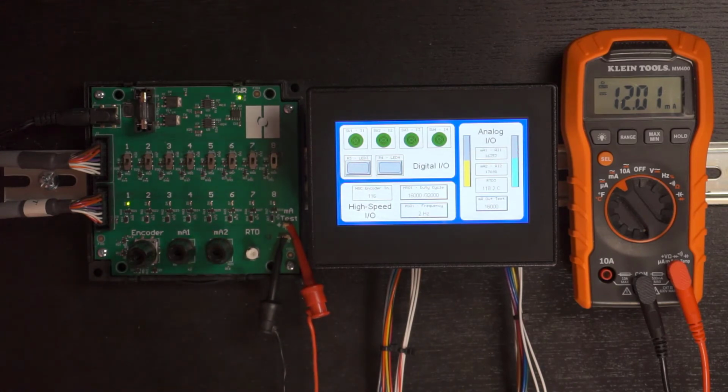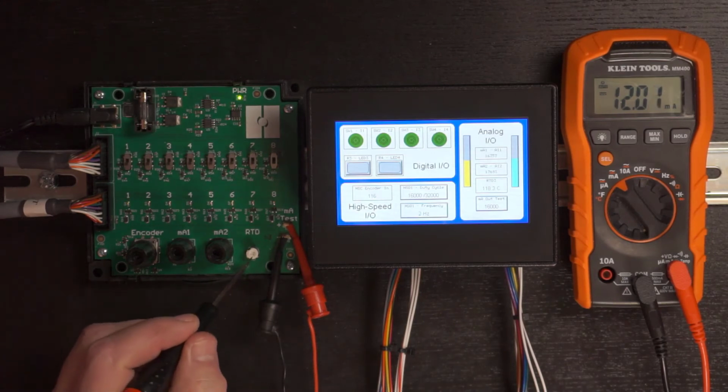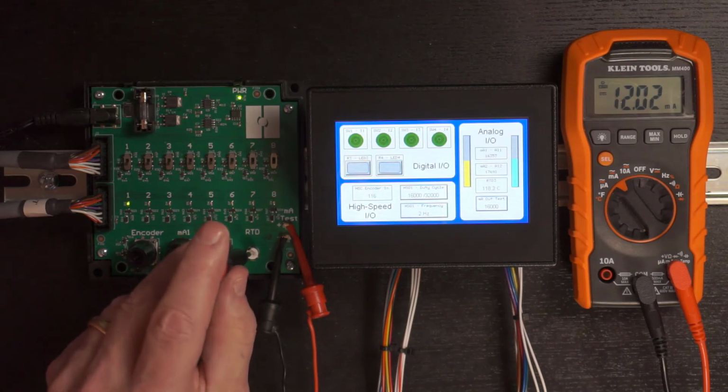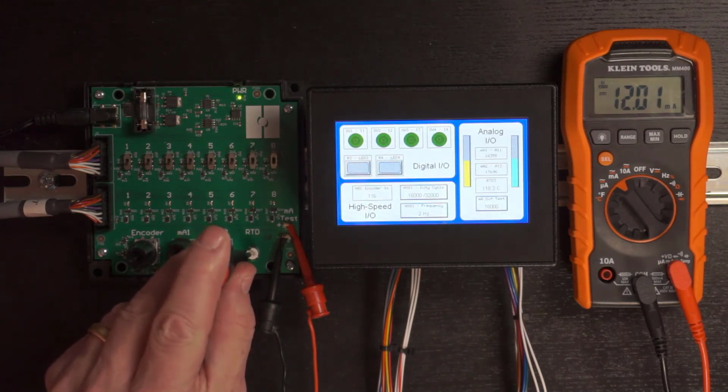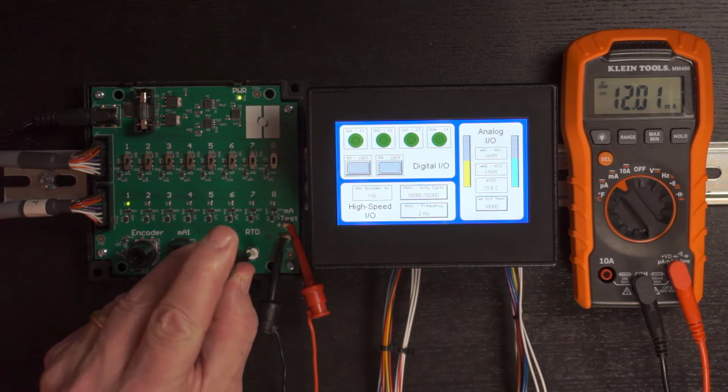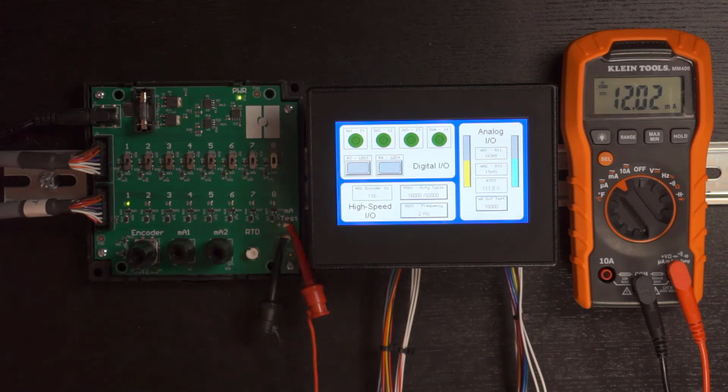And then next we've got our third pot, which has to be operated with a screwdriver. I've just got a small flat screwdriver here. As I move it clockwise, you'll notice the temperature going down. That's shown in the third data field from the top there. And as I go counterclockwise, you'll see the temperature going up. Now, the Micro series supports RTD PT100s from minus 50C to plus 200C. And that simulating pot approximates that range, above and below a little bit.